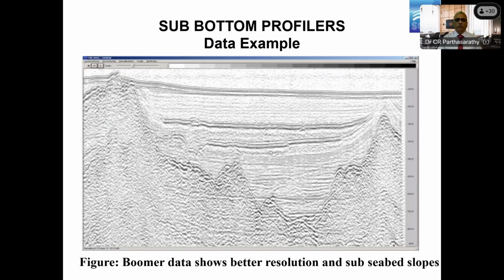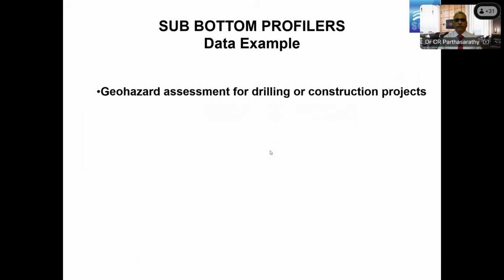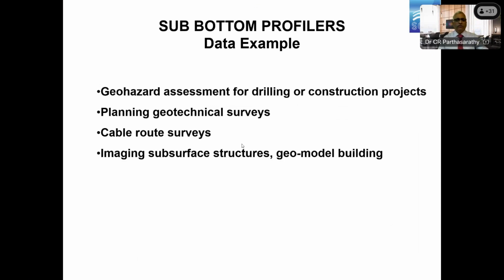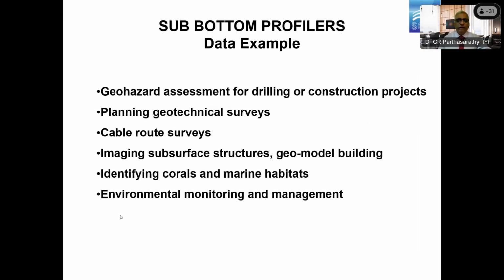So I'll show you one data as well, how the geophysical data help us to take decisions to move the rig outside the influence of the channels. The sub-bottom profile can also assist in geohazard assessment, planning geotechnical surveys, cable route survey, imaging subsurface structures, geomodeling, identifying corals, marine habitats, and so on.